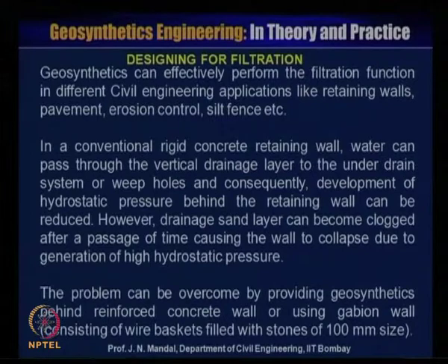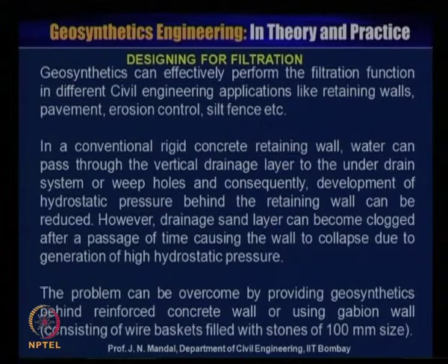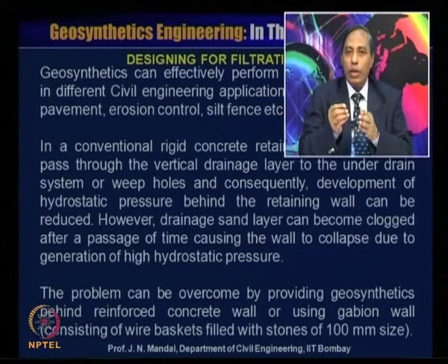Now, designing for filtration. Geosynthetics can effectively perform the filtration function in different civil engineering applications like retaining walls, pavements, erosion control and silt fences. In a conventional rigid concrete retaining wall, water can pass through the vertical drainage layer to the underdrain system or weep holes, and consequently the development of hydrostatic pressure behind the retaining wall can be reduced.